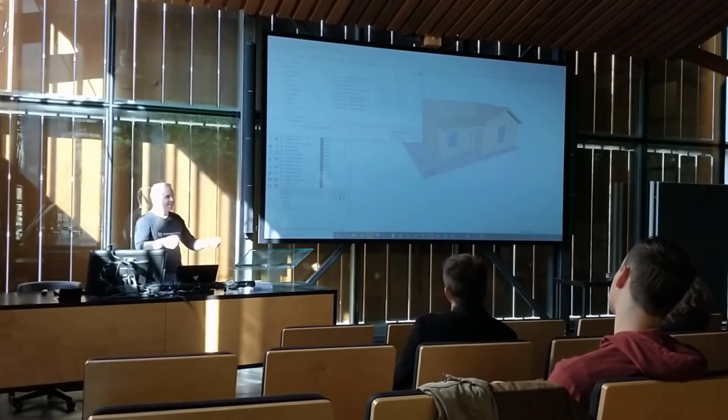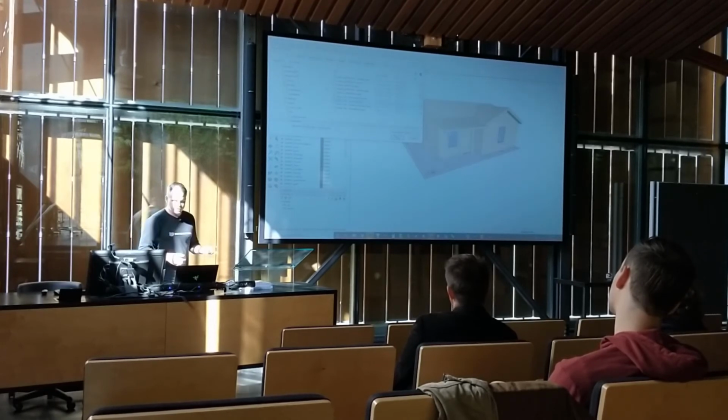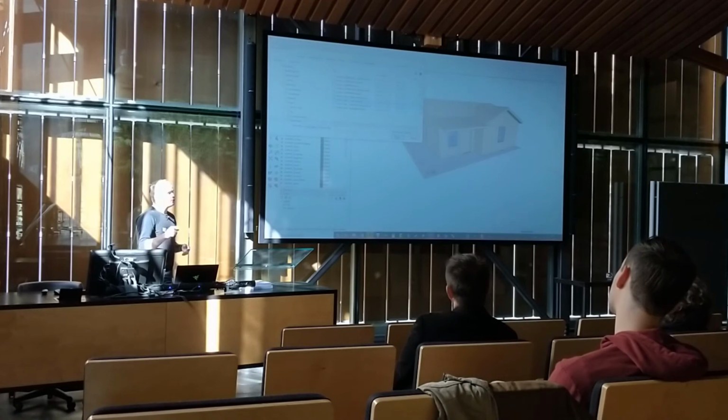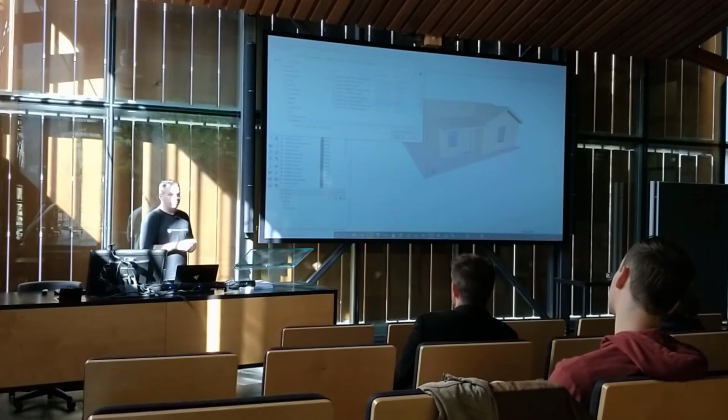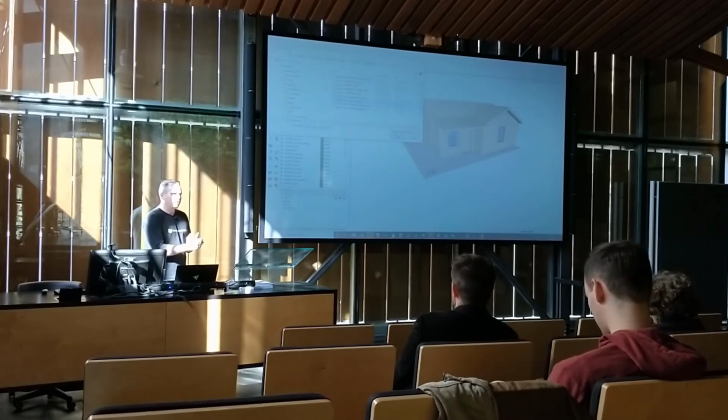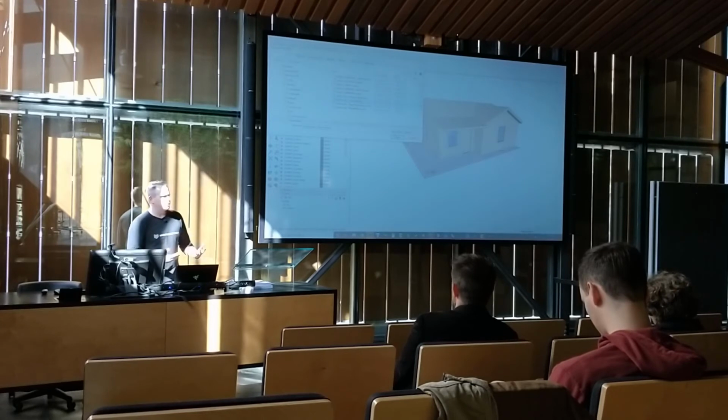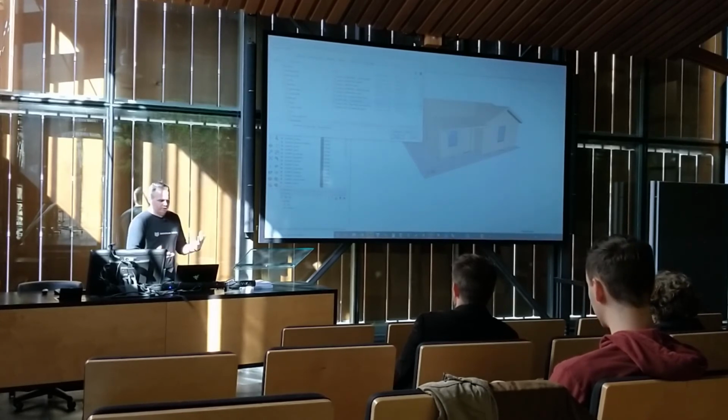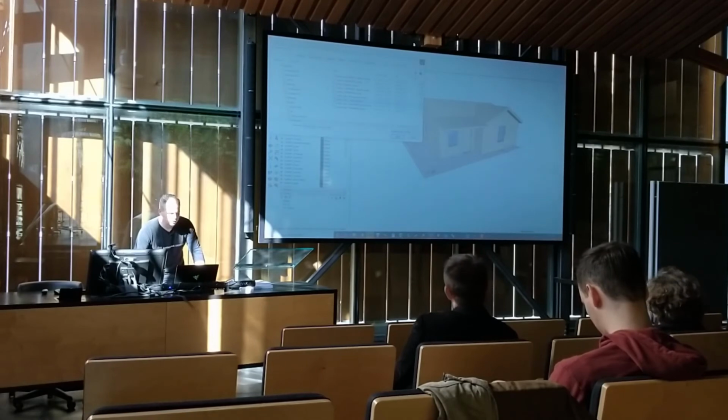Then we have one for Canvas. That's that 3D scanner, which is super cool. It generates existing conditions drawings for Canvas. And then Digital Site Survey is super fun to mess around with. If you import topography, you can hit the Digital Site Survey, and it will chop it up and create a topography map. And then the Placemaker one creates figure ground diagrams, aerial imagery maps, and locator maps. So they're just little tricks where you're like, oh, these guys are using certain layers, and I can automate that. So let's make a drawing. That's what the drawing sets are all about.